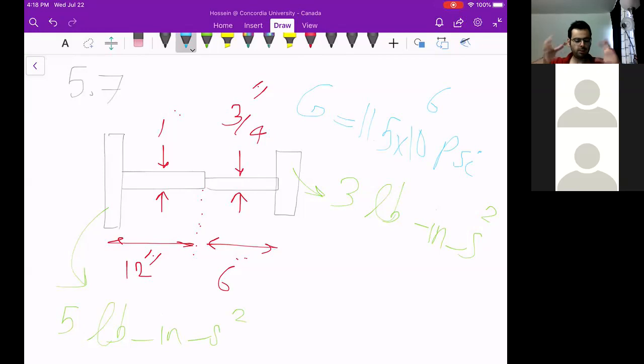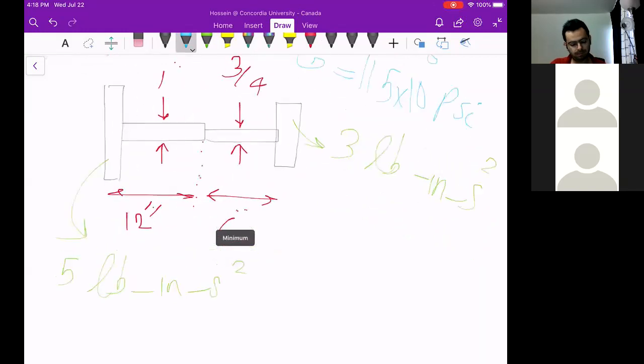Basically, there are 2 disks which can independently rotate, and we are dealing with a 2 degree of freedom system. You can imagine there are 2 masses attached with 2 different torsional stiffnesses, and for the sake of simplicity, we could simplify the 2 springs and substitute them with 1 spring and make our calculation much simpler.